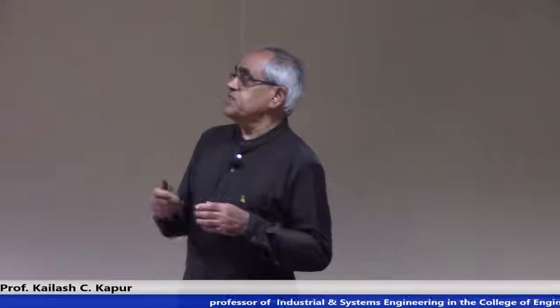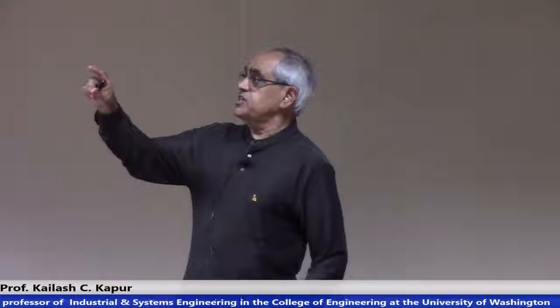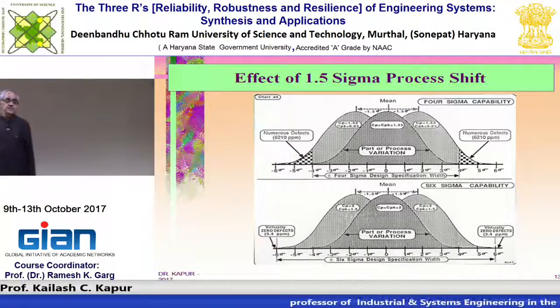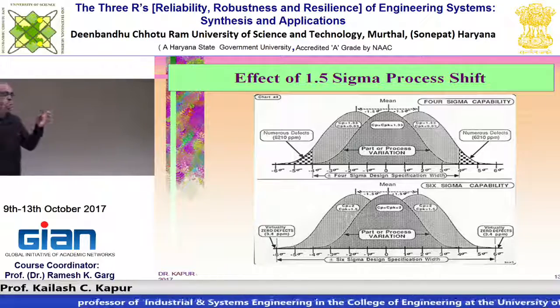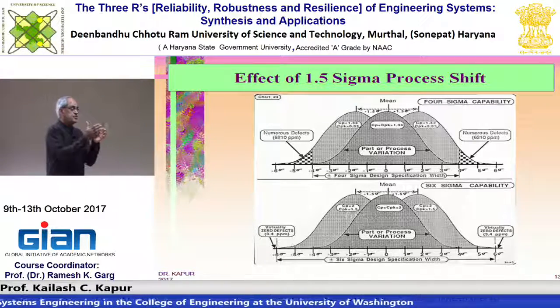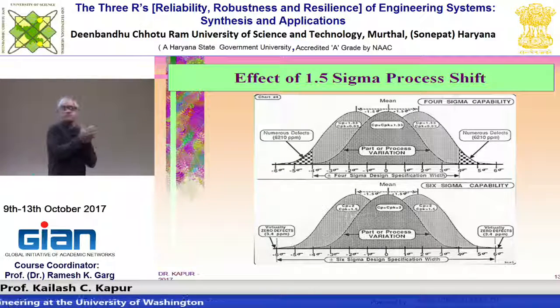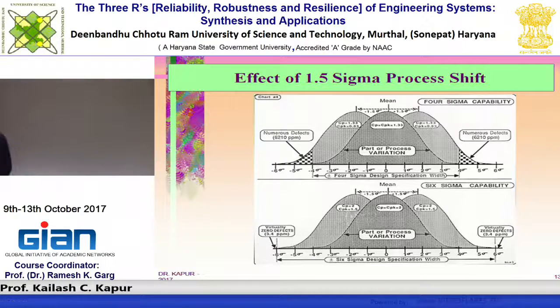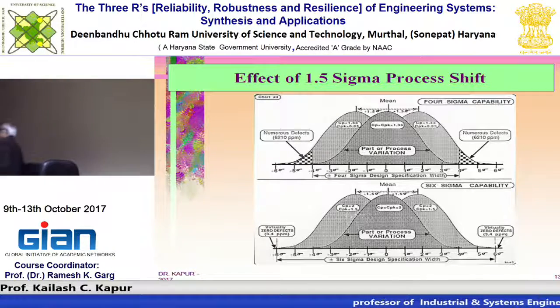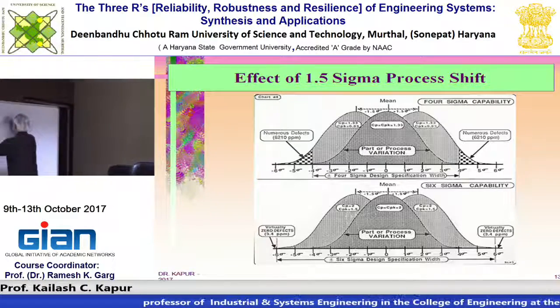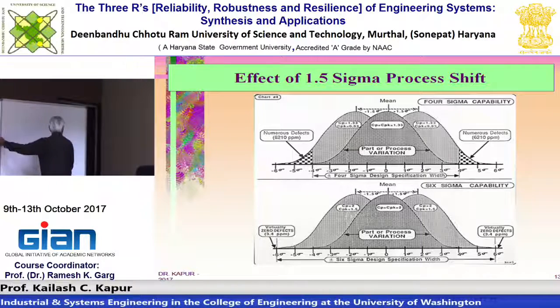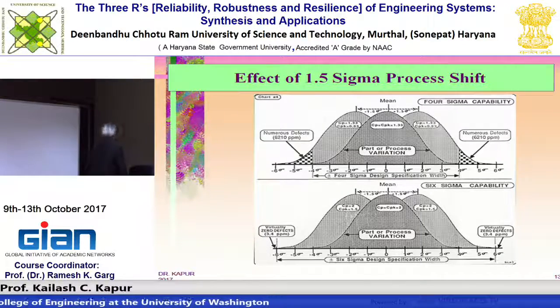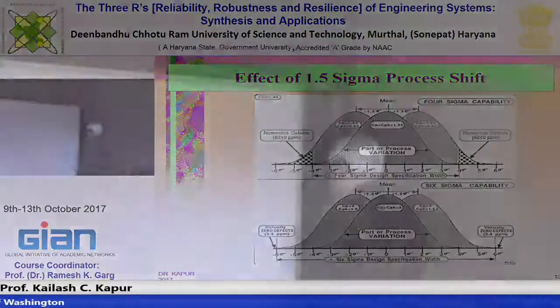There is a concept called, this one we didn't show, the shift in the process. And there is a metric called process capability. The idea in manufacturing these days is that if the designer has some requirement, then you have to decide how capable the process is. And there is a very simple equation that one can develop. Then I can give you a little bit of motivation for that equation. It's a little mathematical, but maybe you can relate to it.